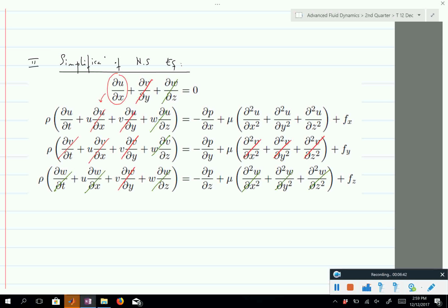But think about it, acceleration is the time derivative of a vector. So you can either change the magnitude of the vector, which means you're going straight and your velocity increases. But because the flow is incompressible and you are unidirectional, this is not possible. Right? This is equal to 0. And if your flow is unidirectional, then you cannot change directions. So because you are incompressible and you constrain the flow to move in just one direction, then all of the effects of inertia are out.